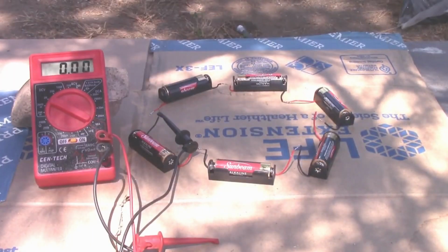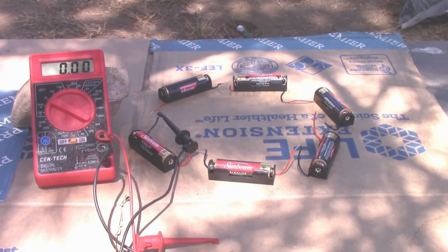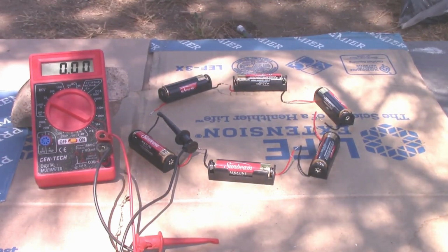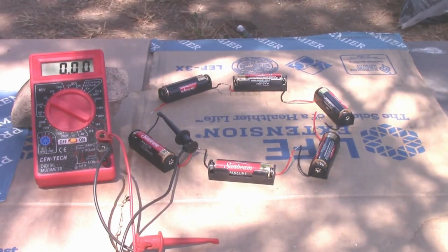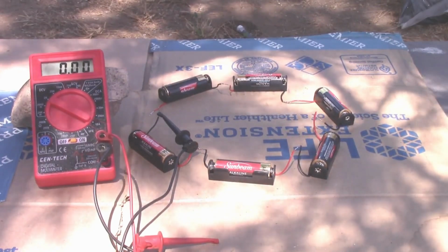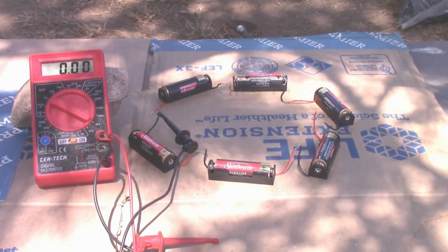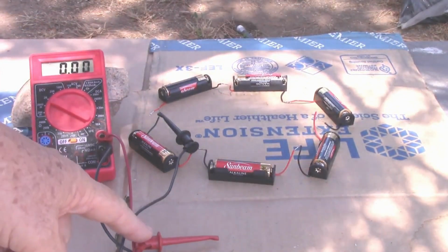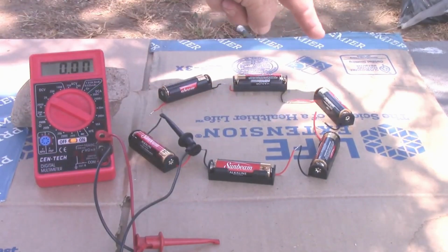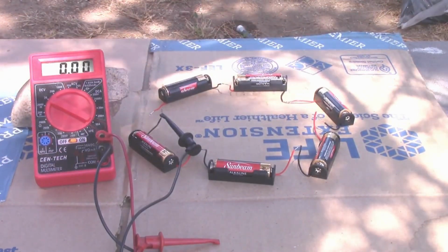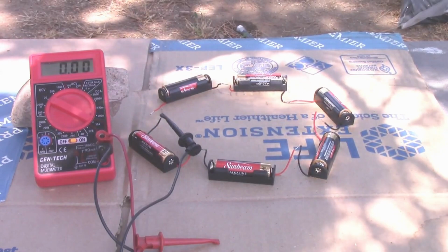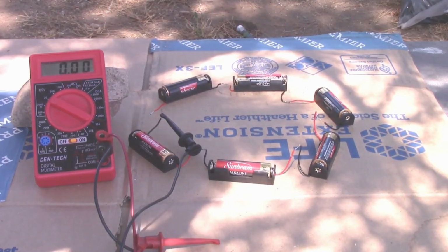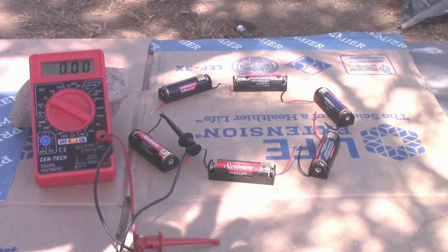Okay, ladies and gentlemen, here is the test. The question is, what happens if you put a number of batteries into a loop? And what I'm trying to find out here is if an application of Thevenin's theorem and Kirchhoff's voltage law works. The theory is that when I have the loop broken, as you can see right here, I have no connection in the loop. As I move the red lead of this voltmeter to more and more positive sides of the battery, I should see a higher and higher voltage. However, with a proper application of Thevenin's theorem and Kirchhoff's voltage law, whatever voltage I'm measuring with this open loop should go to 0 if I close the loop.